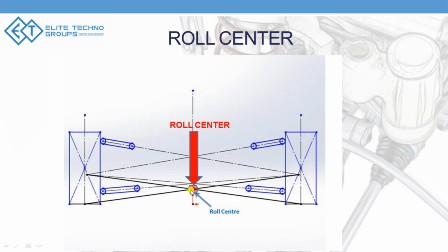And what is the purpose of roll center? Okay, so for example, if your CG is somewhere here, assuming that your center of gravity is around here and your roll center is along here, right? So this distance is the one you want to maintain as small as possible, because rolling motion, as we have seen in today's first slide, is how your car body moves in this direction, and that depends on this distance.